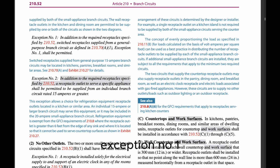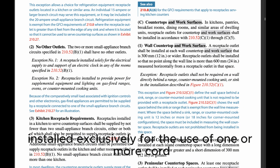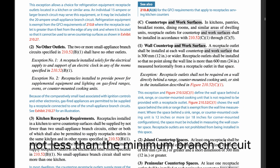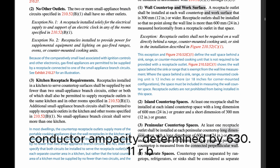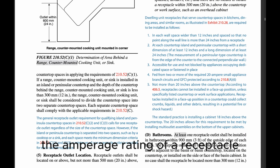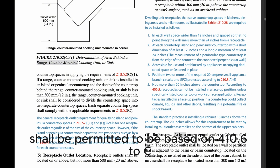Exception No. 1: Receptacles installed exclusively for the use of one or more cord-and-plug-connected arc welders shall be permitted to have ampere ratings not less than the minimum branch-circuit conductor ampacity determined by 630.11(A) or (B) for arc welders. Exception No. 2: The ampere rating of a receptacle installed for electric discharge lighting shall be permitted to be based on 410.62(C).